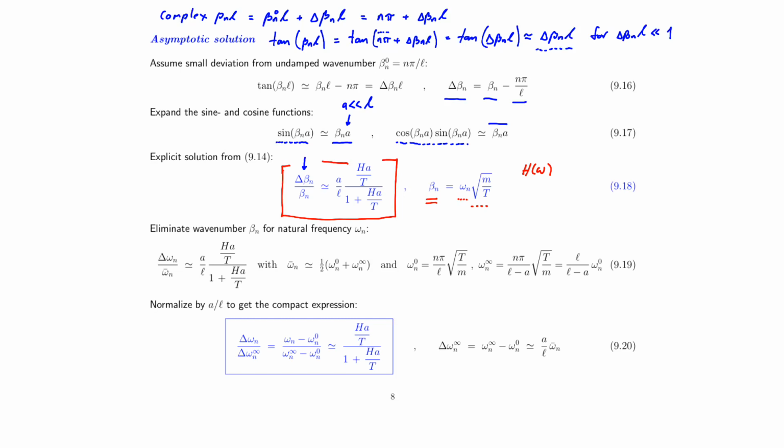And later in this lecture we're going to have a look at general damping of structures, and in that case it's very convenient to have the natural frequency omega as the solution parameter. So therefore we switch the left-hand side to omega, so that the entire expression is now a solution in the natural frequency omega. For the beta function here, we actually had the complex beta in the denominator on the right-hand side, on the left-hand side.